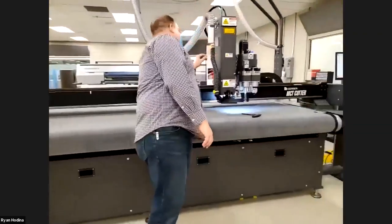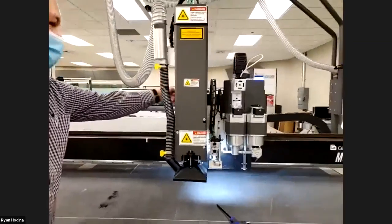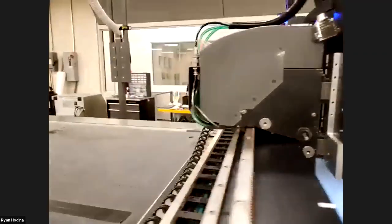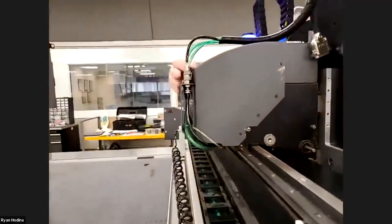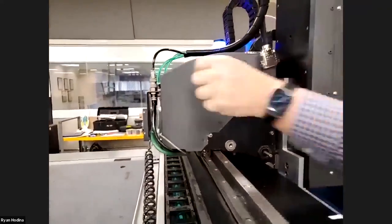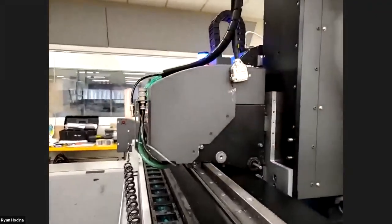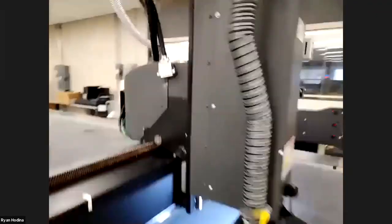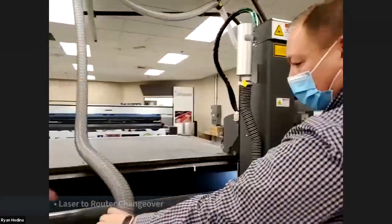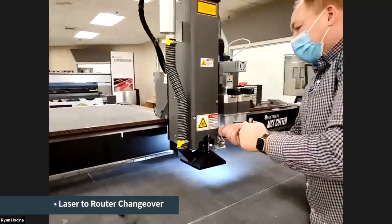So for the laser removal, it's pretty simple. We've got one power cord in the back here, and we've got 2 coolant lines. Those are the coolant lines coming from the chiller to cool the laser. And we've got one compressor hose at the top. Then it's just simply 3 bolts, and that's it.